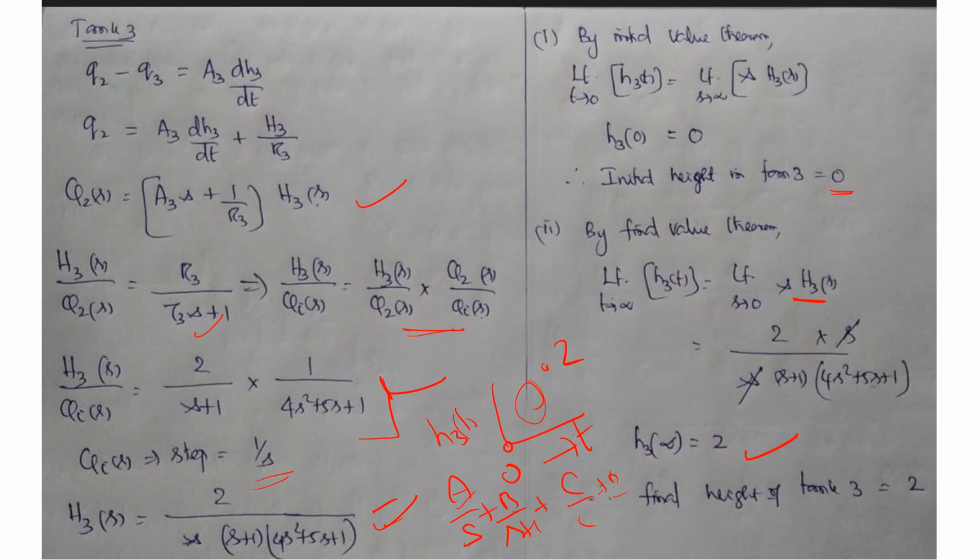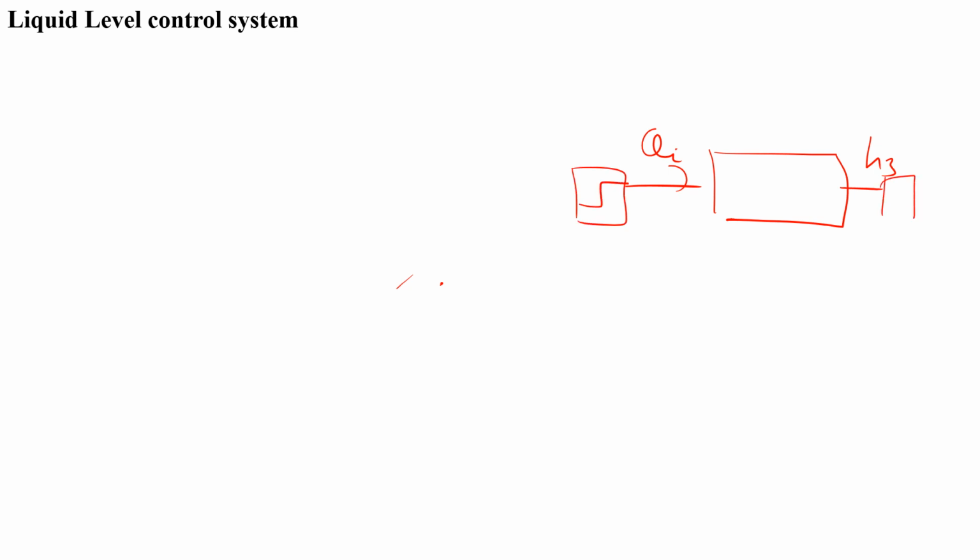Okay. So in MATLAB, take Simulink. In the Simulink, put the tank expression. This is H3 and then this is Qi. So take the tank expression and then here you give a step input. Then you can add the scope. And then click simulation, you will get the response. So you can check the response against the same.